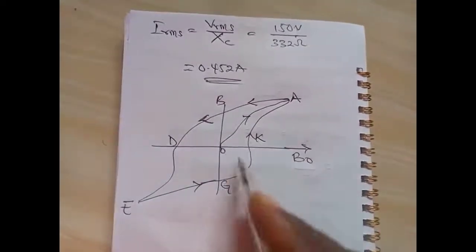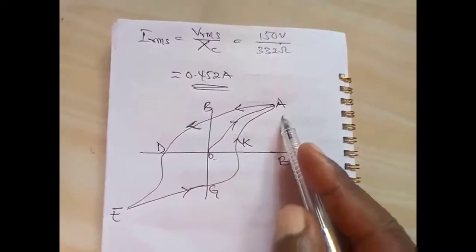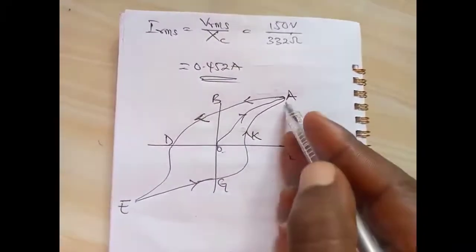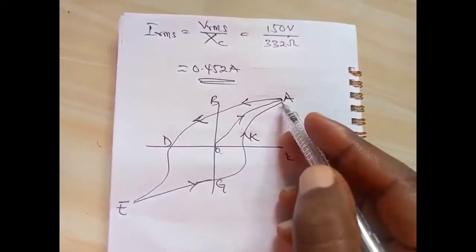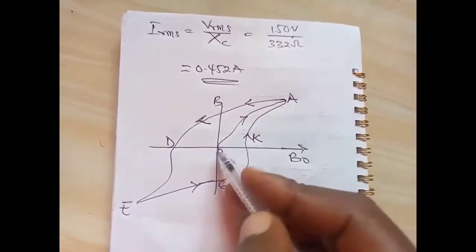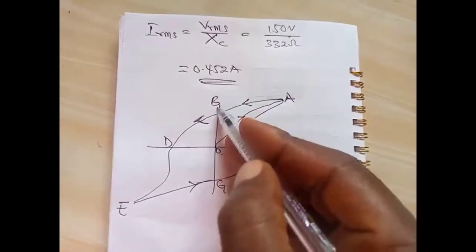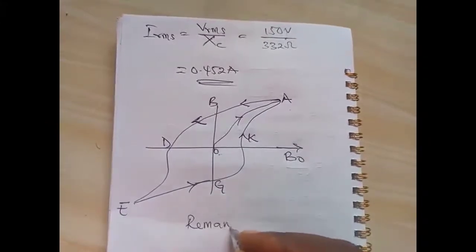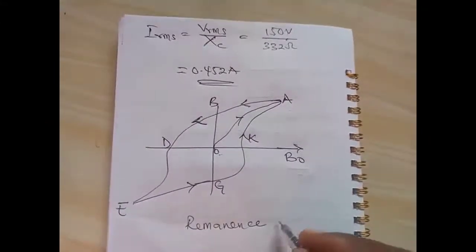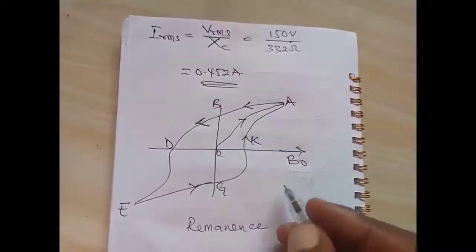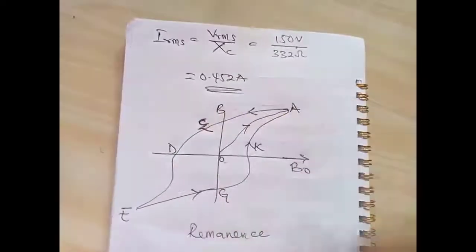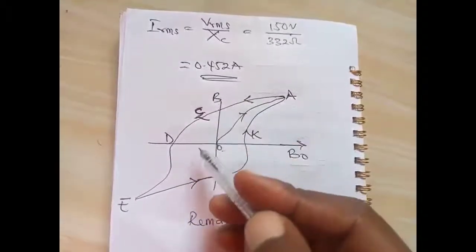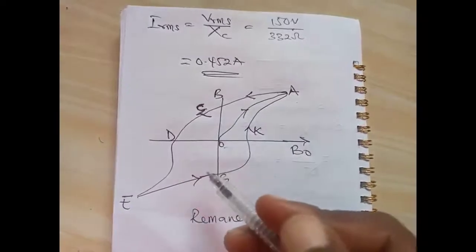Curve OA shows initial magnetization of the ferromagnetic material until saturation is reached at this point A. When the flux is reduced to 0, B has a value called remanence, at this point C. So to reduce B to 0, we must forcibly disalign the domains by using a reverse external field.